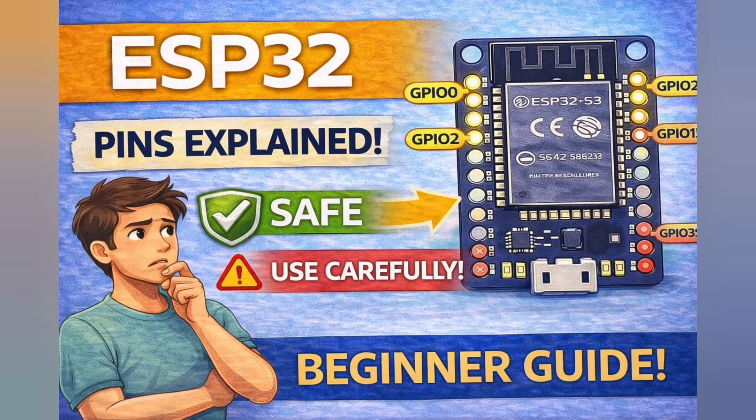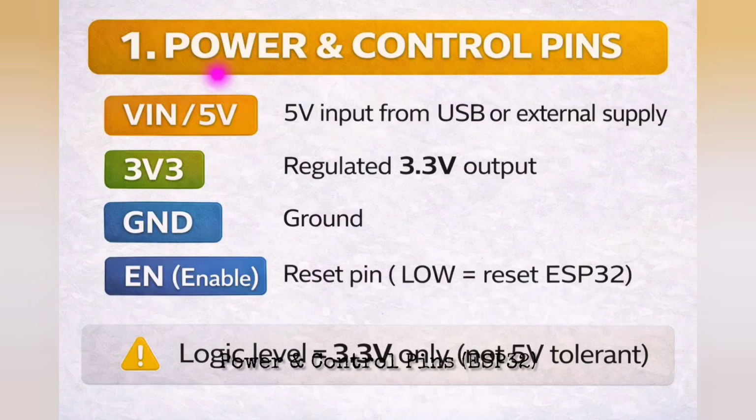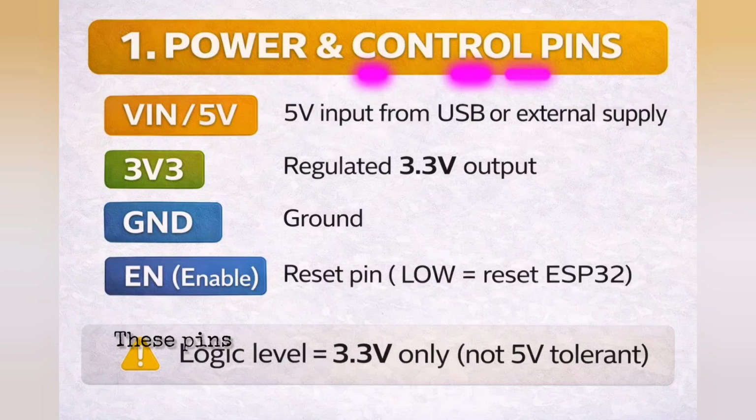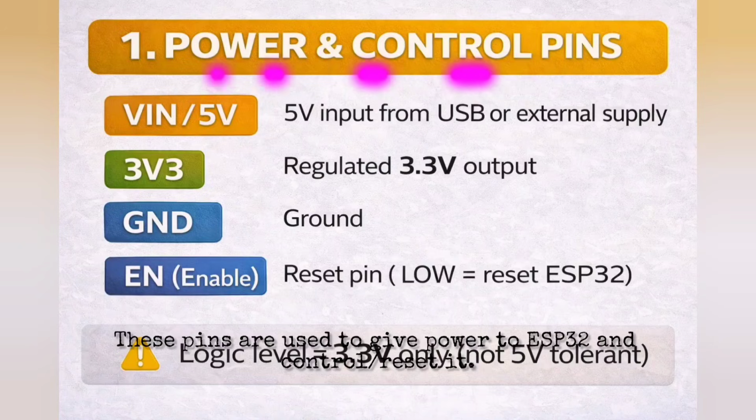Today we are going to learn about ESP32 pins in a very simple way, including safe pins, boot pins, communication pins, and special pins. Power and control pins, ESP32. These pins are used to give power to ESP32 and control reset it.